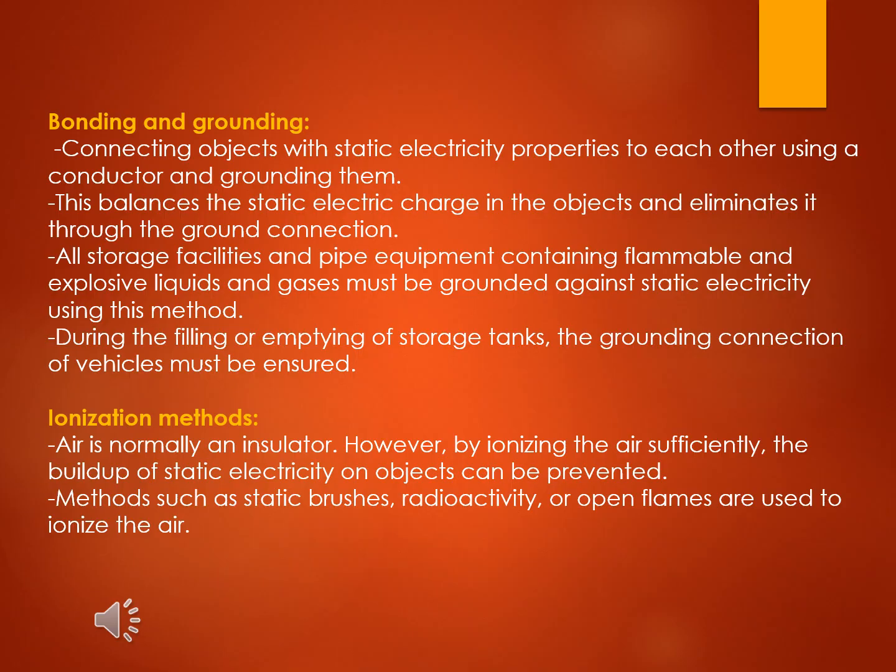For ionization methods, air is normally an insulator. However, by ionizing the air sufficiently, the buildup of static electricity on objects can be prevented. Methods such as static brushes, radioactivity, or open flames are used to ionize the air.